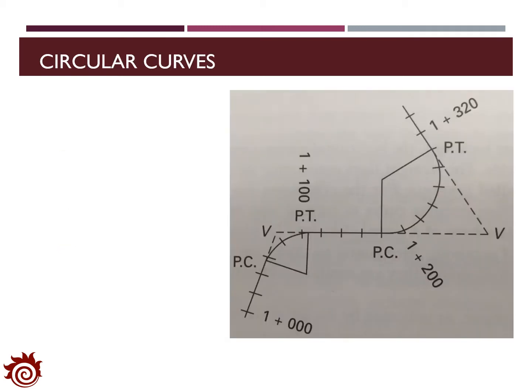First, let's go through the circular connection of the straight segments for horizontal curves. The figure here shows two horizontal curves for the connection of three segments, which would be the horizontal curve 1 and horizontal curve 2. In this figure, you can see three different types of the points, PC, V, and PT. Here, PC is the point of curve, which is the start point of the horizontal curve, and it will connect the curve with the preceding line.